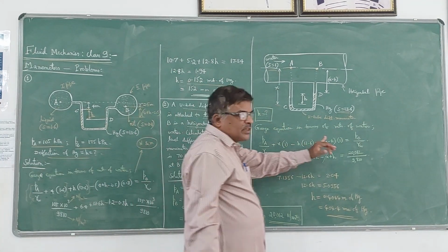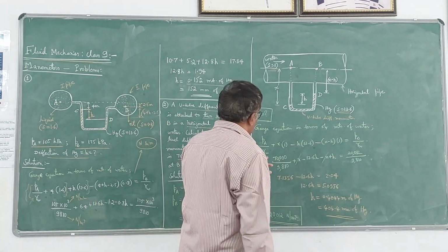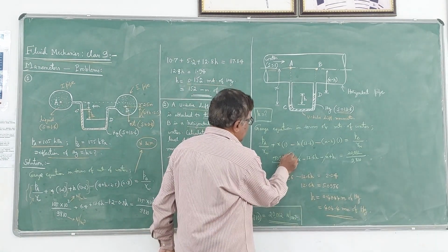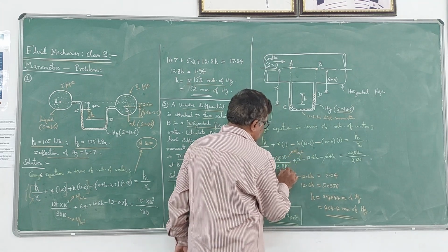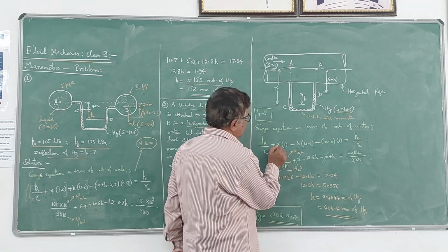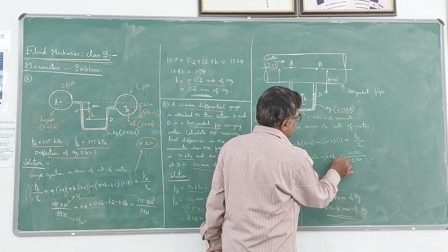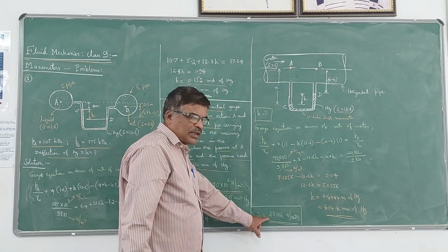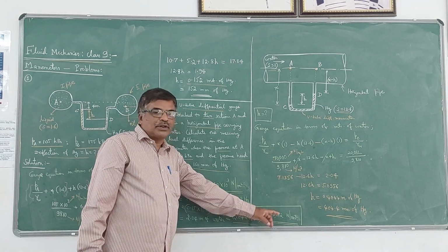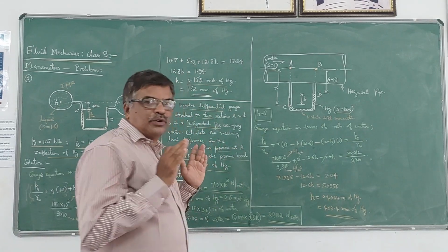Now, once you write the gauge equation, substitute the values in Newtons and meters, simplify and get the unknown. So PA is given as 70 into 10 cube, meaning 70,000 Newton per meter square. This is the unit. Specific weight of water is 9,810 Newton per meter cube. Then plus x into 1 is x, minus 13.6 h, minus x plus h, is equal to PB, which is this value actually. Please note, this is very important. We have to convert 150 millimeters of mercury to Newton per meter square of water, because both the pressures should be in the same units and with respect to the same fluid.